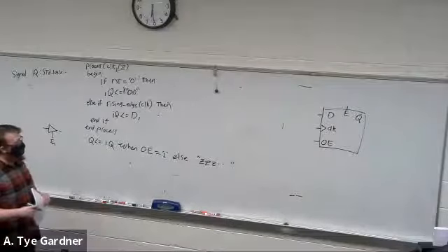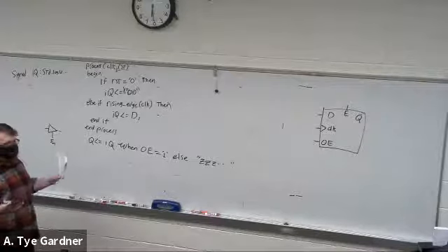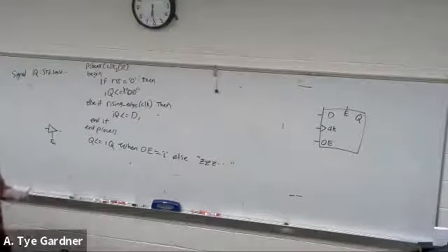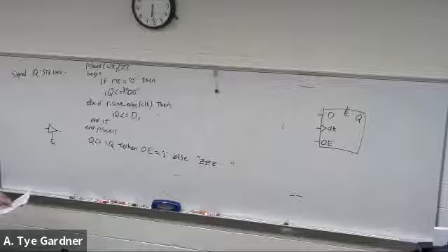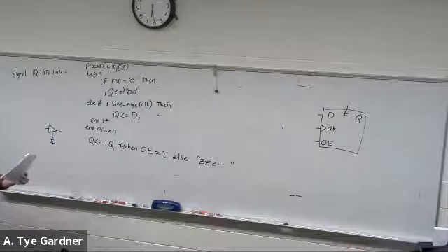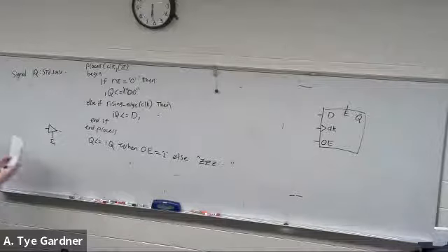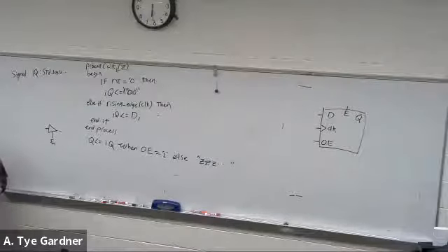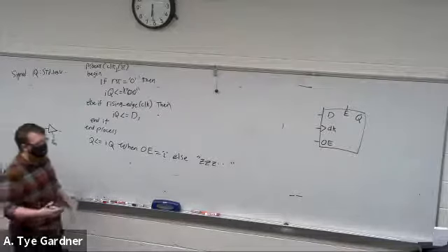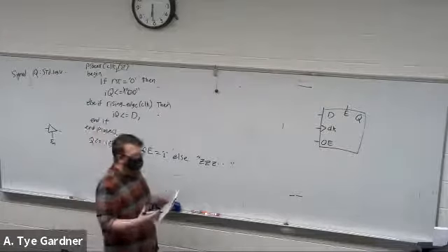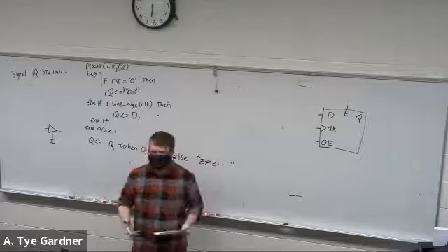Okay, let's talk a little bit about the applications here, some of the other stuff we can do with the flip-flops, right? So we started off with the SR latch, we made it into a D latch, turned that into the master-slave relationship between the two D latches, and ended up with the D flip-flop. What can we do with the D flip-flop? Well, we have this idea of clock dividers.